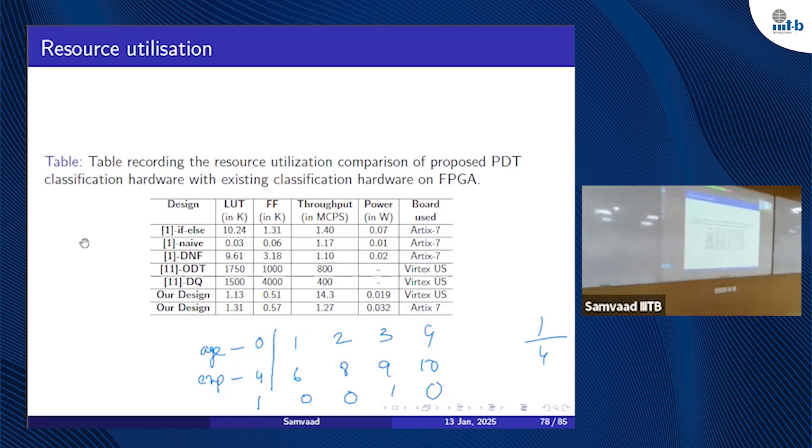What about when you implemented those multiple feature based designs, like you use extra FPGA? No, extra FPGA I have not used, only one FPGA. No, I mean the working part of it. It would have consumed additional power. So in that respect, it's for the number of features when you increase. Yeah, if I increase the number of features, the power will increase, because I am doing it in parallel for all the features. So more comparators, more multiplexers. I have tested for 6-7 maximum. If you go till 12 also, there will not be much higher power. But if you go for 32-64 features, then your power will increase, because there are only small comparators and gates there, right?